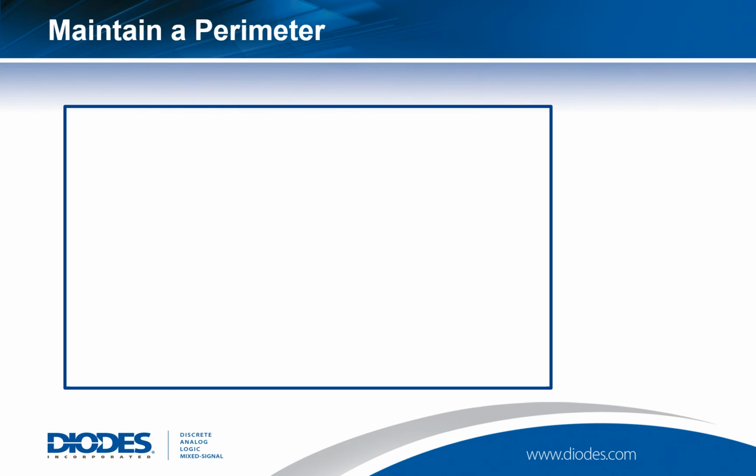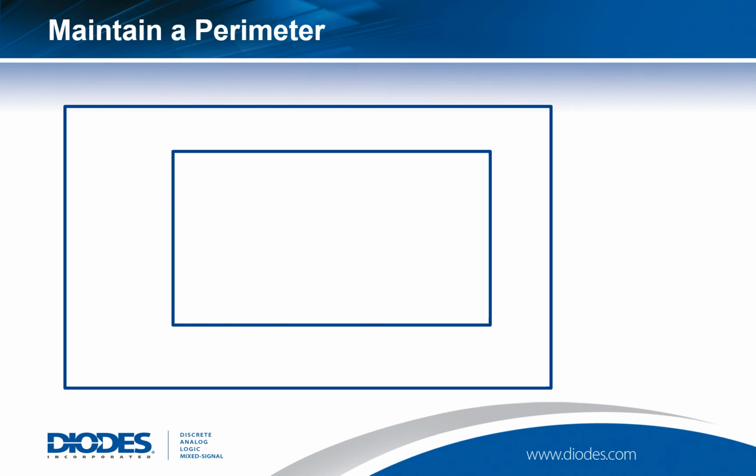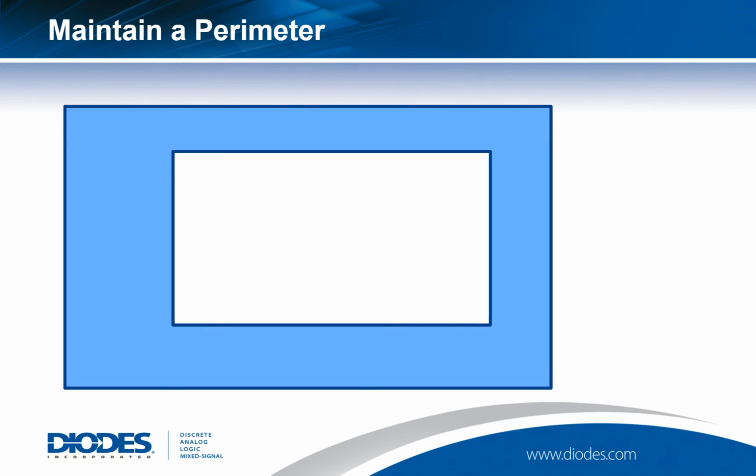Let's consider an overall PCB design. A good approach is to maintain a perimeter. By that I mean place any high-speed signals, high-speed circuits and sensitive items as close to the middle of the PCB as you can. Keep them away from the edges. We discussed the concept of protection margins previously, and now let's have a protection perimeter. And in this area we could put low speed, DC power supplies, this kind of thing. It doesn't have to be empty, but keep the high speed and sensitive stuff away from it.